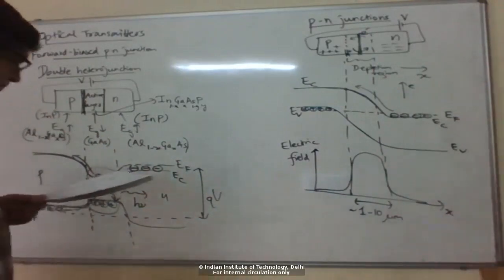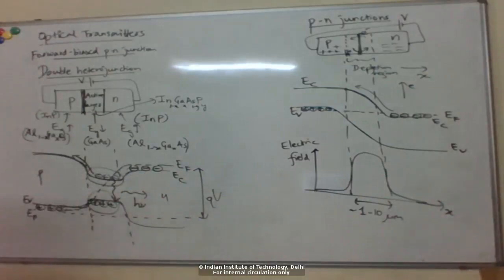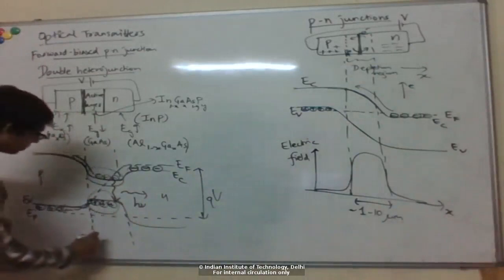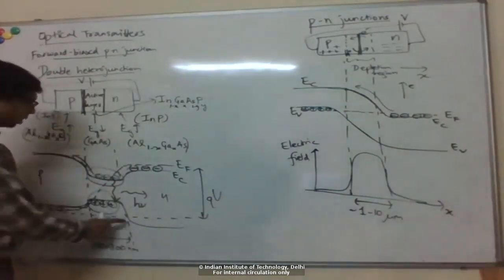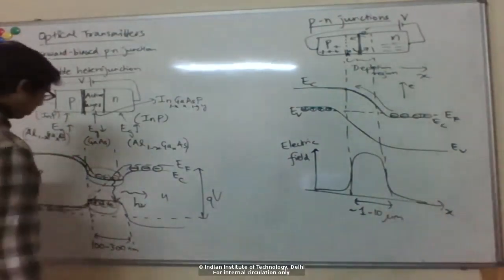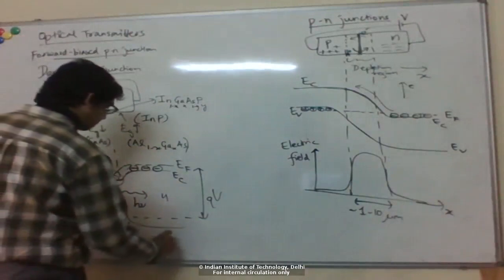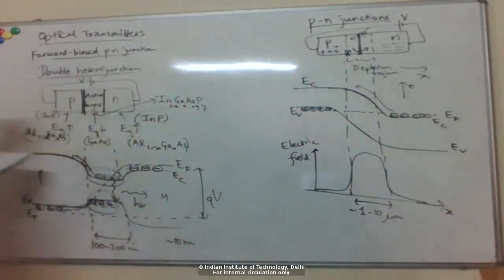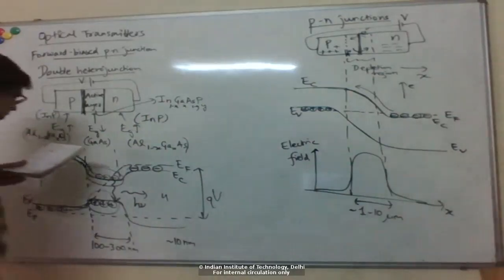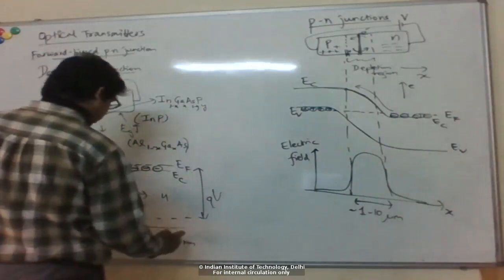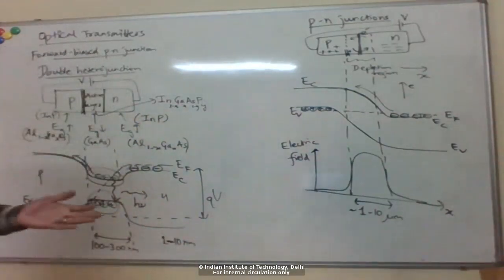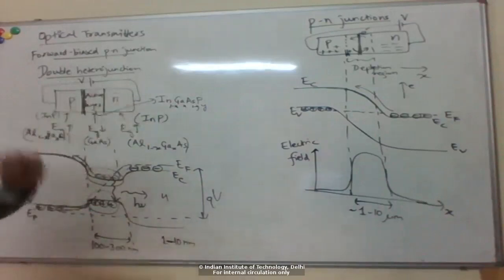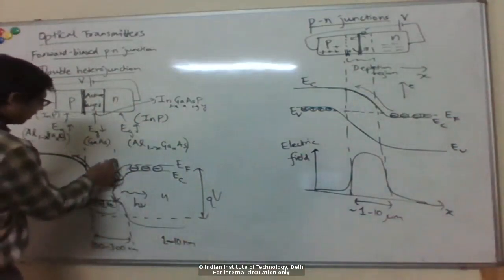And not only that, there is an additional benefit that one got for free. So typically this active layer thickness is about, let's say, 100 to 300 nanometer, in that range. Okay, so maximum maybe up to half a micron. Sometimes this can be made really small also, like less than 100, like tens of nanometer. Sometimes you go down to like 10 nanometer, for example. Okay, and so if you go down to the region of a few nanometers, there is a technique known as molecular beam epitaxy by which you can grow atomic layers one at a time. So you can control the thickness down to like 1 nanometer, for example. So using that, you can make really thin devices.